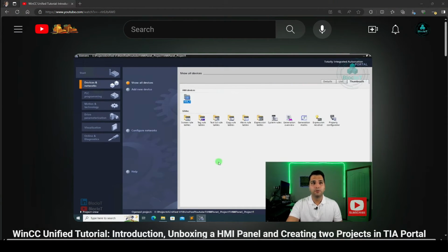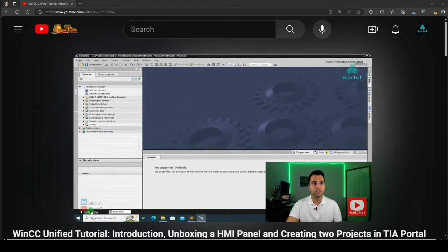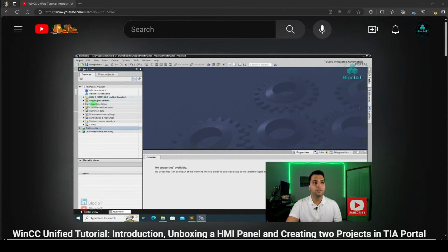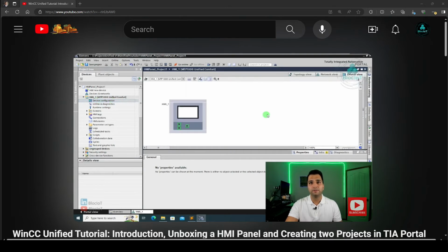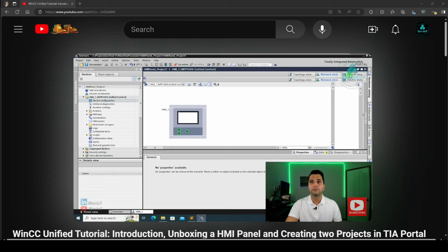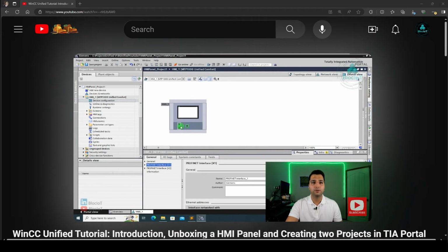Programming a Unified Basic panel is exactly similar to programming a Unified Comfort panel. You just need to select a different hardware from the hardware catalog. So to learn how to program a UBP similar to UCPs, please check the other video, in which we explain a few examples of how to program a Unified Comfort panel in TIA Portal. Just please keep in mind, the Unified Basic panels are only available from TIA Portal version 19.